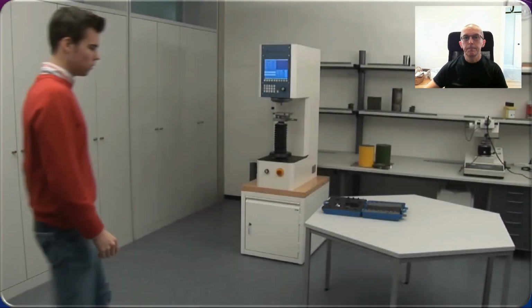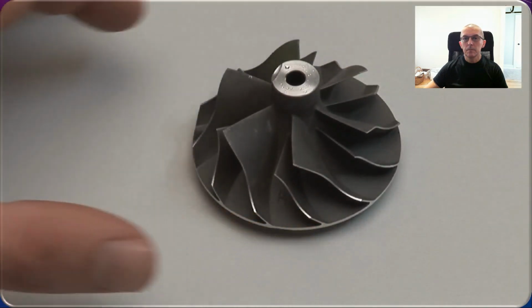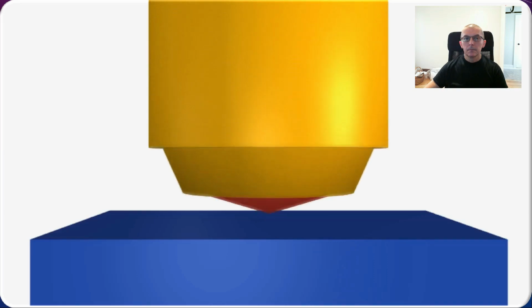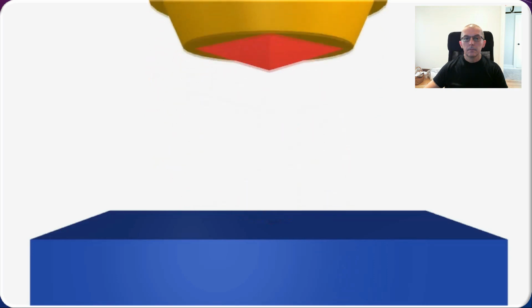The hardness of a compressor wheel for a turbocharger is to be measured using the Vickers method. The main principle of this hardness testing method is to press a pyramid-shaped diamond indenter with an exactly defined force onto the test piece and then to evaluate the surface area of the indentation.